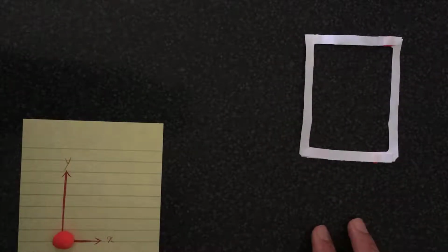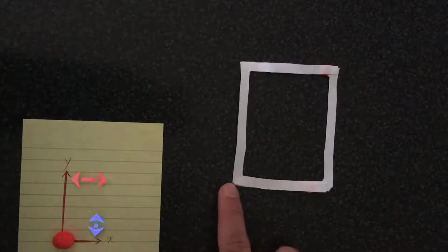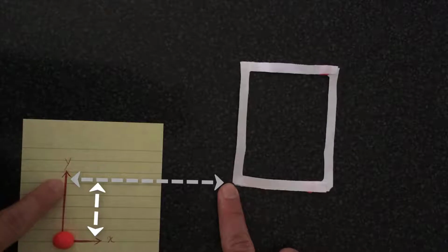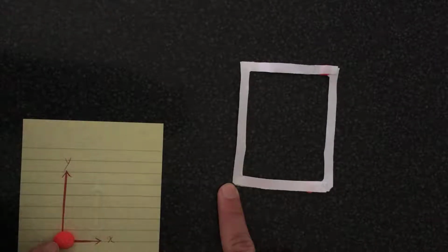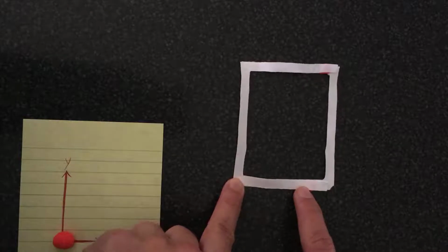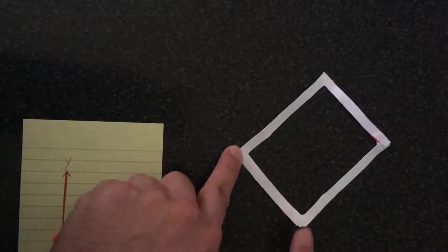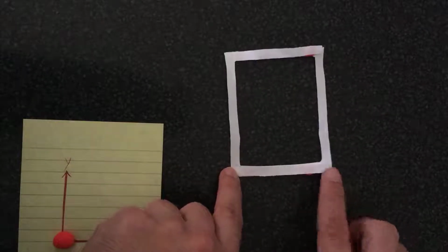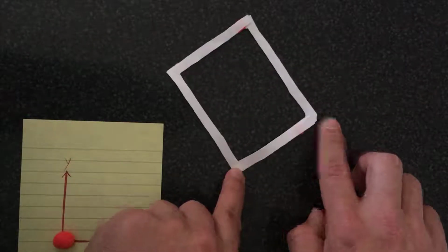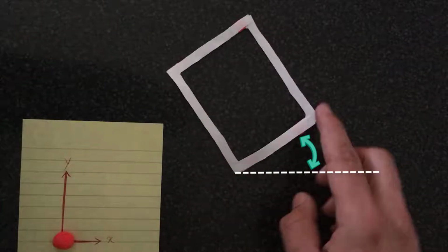Unless I specify the exact position, the application doesn't know where to create the sketch. So that is the first thing to consider. Both x and y coordinates of this point should be specified. Another thing is whether this line is horizontal or inclined. Maybe the angle is something else. Maybe it is like this. Until I clarify the exact dimensions, the geometry will not be fully defined, so the orientation should be specified.